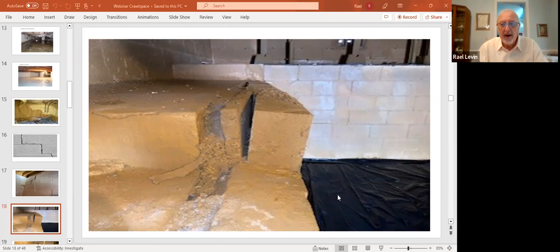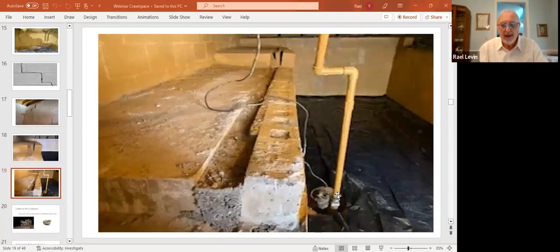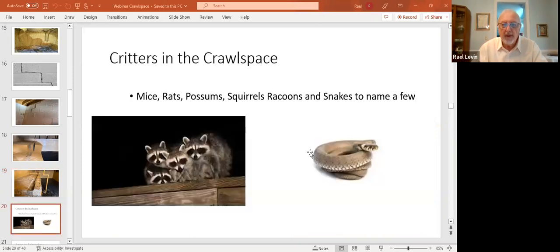We do see a vapor barrier down here, and this is another way that it can be addressed. So if we're still getting moisture into our crawl space and we want to deal with any kind of mold growth, we have a pump right here that's installed down in a well, in a low part of the actual crawl space area. And we should have a designated electrical outlet, perhaps even a GFI, that's connected to the pump. And when the float comes up in this area, when it starts to fill up, it'll eject the water out to the exterior of the home.